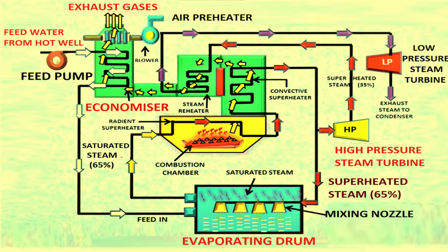The nozzles which distribute the superheated steam throughout the water in the evaporator drum are of special design and avoid priming and noise. This boiler can carry higher salt concentration than any other type and is more compact than indirectly heated boilers having natural circulation. These qualities fit it for land or sea transport power generation.